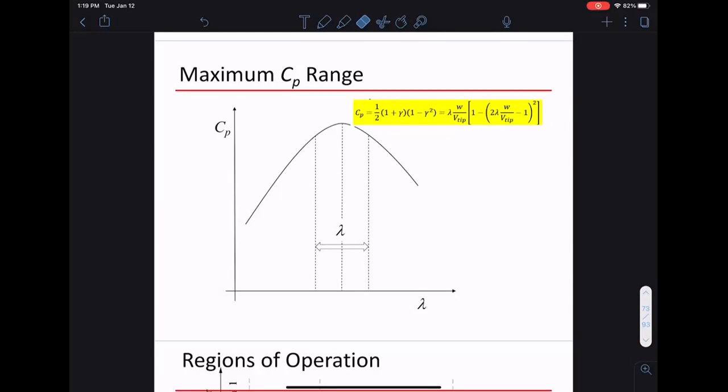So our goal in controlling the turbine is to make sure the turn rate of the turbine hits this sweet spot. We want the turbine to turn at the right speed so I can extract the most power out of it. How you do that is you control the pitch.